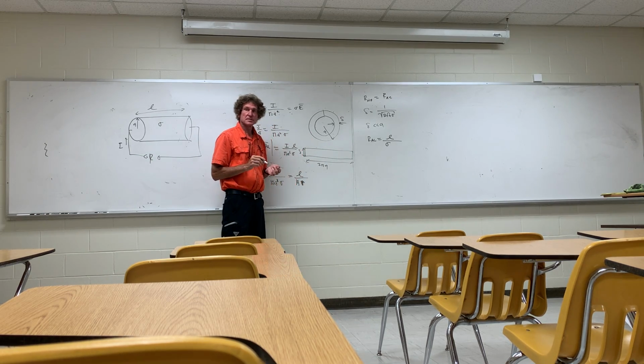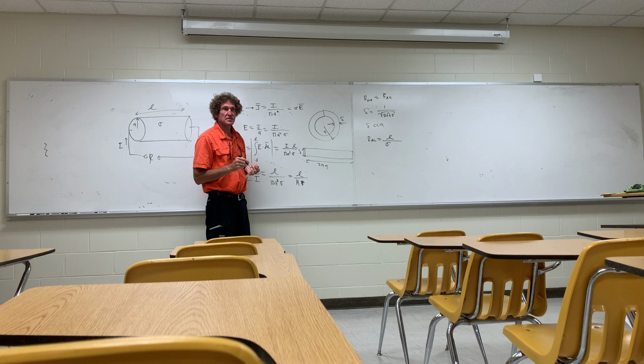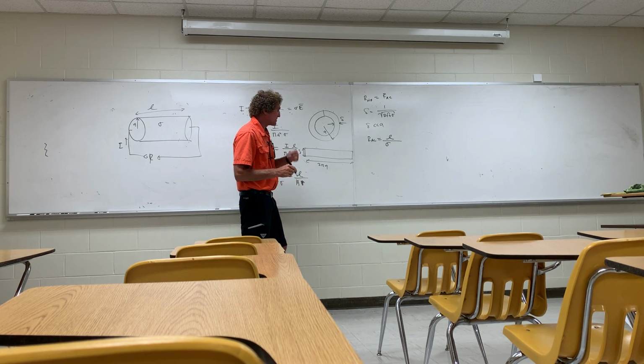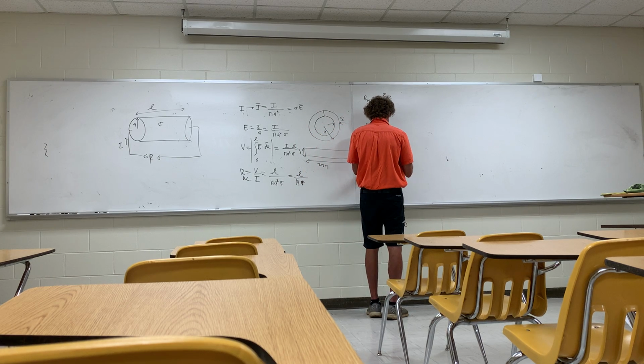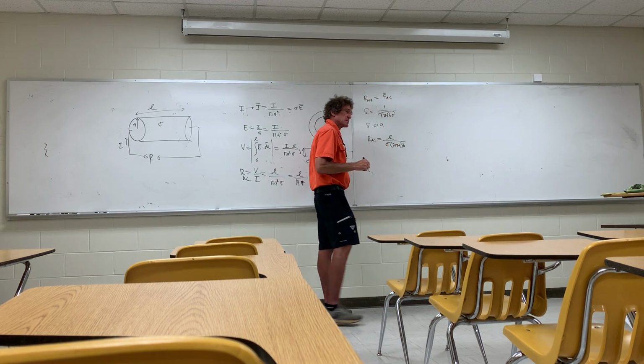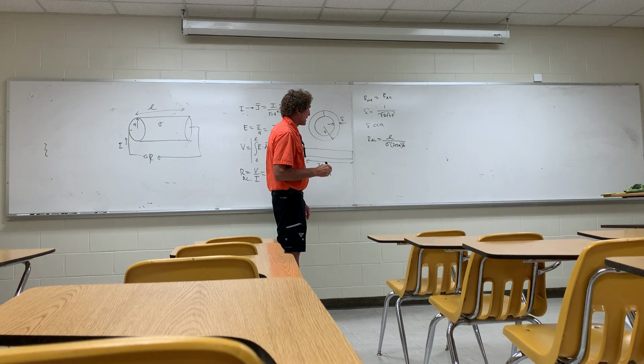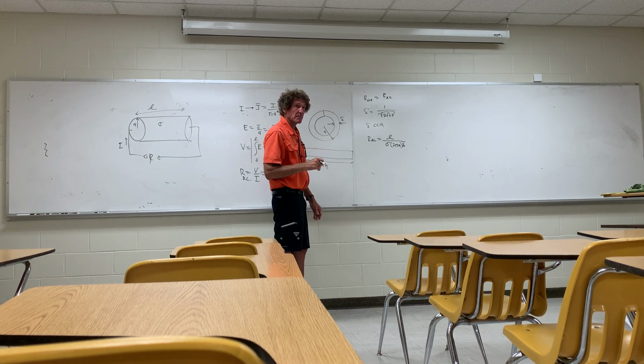Can you all imagine that, guys? Take a good look and just let it sink in, right? Remember going through this before, everybody? All right, now that means the area itself is skin depth times 2 pi A. We could do it another way, but this is the easiest. So it's 2 pi A times the skin depth. And that's the AC resistance. I'm just going to leave skin depth there. We could play with this and change it a little bit. That's it. So R_AC, if the skin depth is much less than A, is given by that.